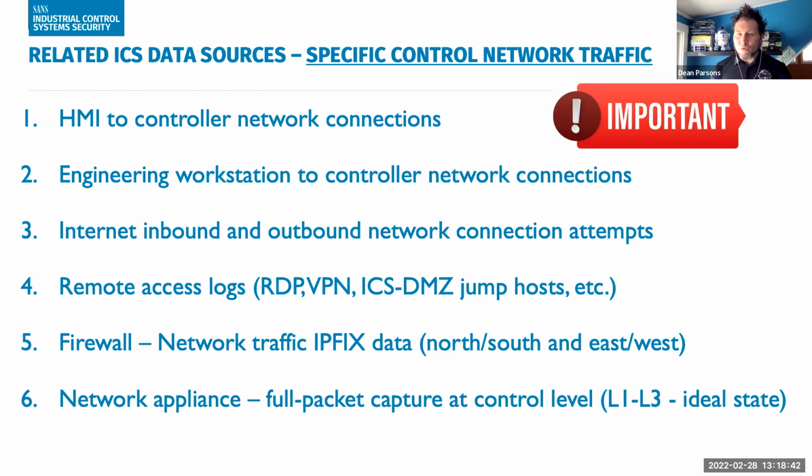And of course, in number 5, we're talking about, again, the north-south, but also the east-west traffic. So not only is there an HMI going to the internet, we also want to understand, from the PLC level or engineering workstation level, are those devices communicating back and forth laterally through the network as well? And again, just a reminder, if we only get the IPFIX data, so the IP source, destination, protocol and port, that's definitely helpful, but wherever we can for hunting, it'd be excellent to have a full packet capture. And I'll show you in a minute why that's the case.